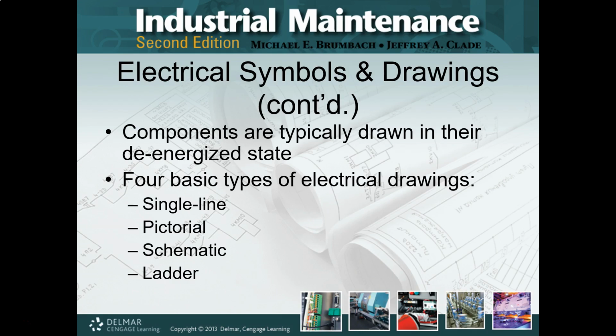Now, schematics are usually drawn so they emphasize the electrical connections, and it gives you a broad picture, literally, of what's going on. With schematics, if you get comfortable with reading them, you can start determining a sequence of operation. But schematics' big claim to fame is for troubleshooting. It allows you to trace out lines relatively easily to see where things are going, specifically where the wire is going and what component is supposed to be at the end of that wire.